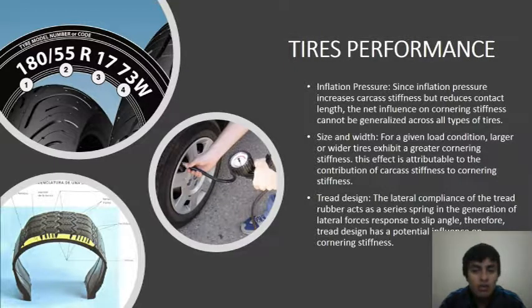The third tire performance factor is tire design, because the lateral components of the tread rubber act as a series spring in the generation of lateral force in response to slip angle. Therefore, tread design has a potential influence on the cornering stiffness.